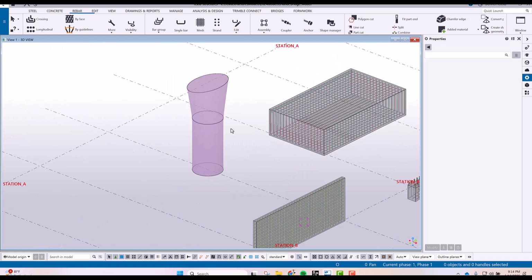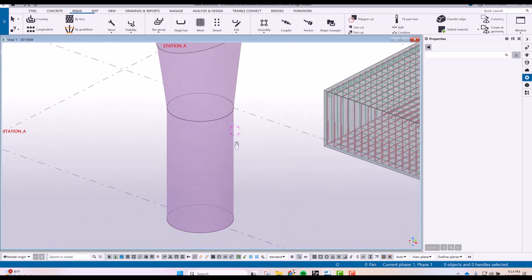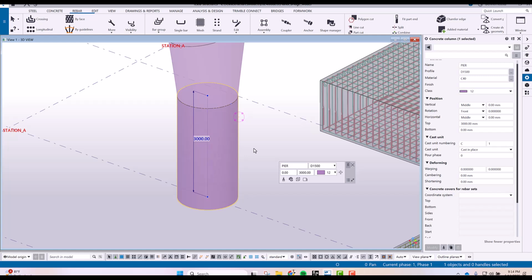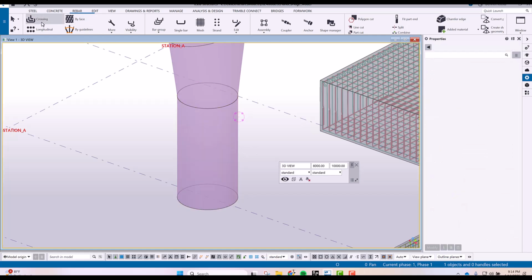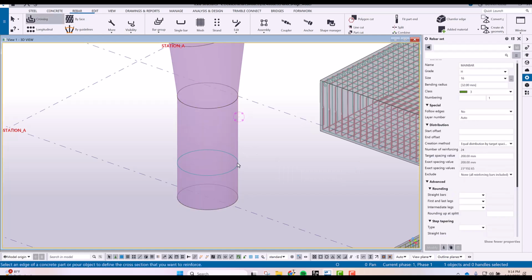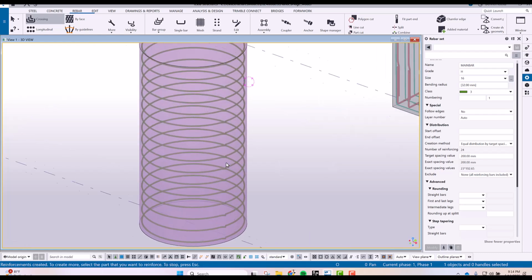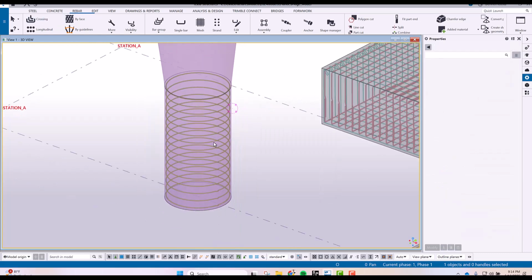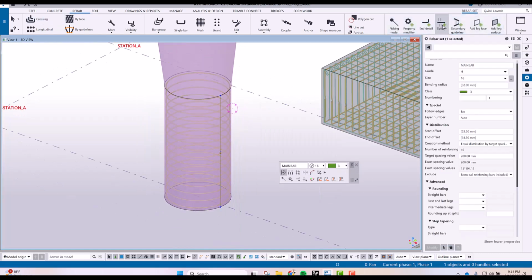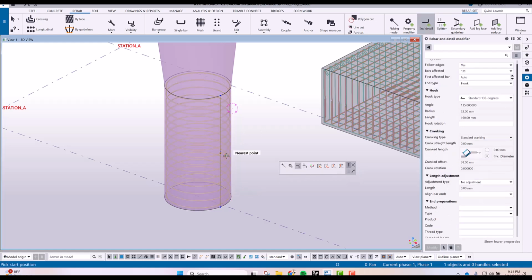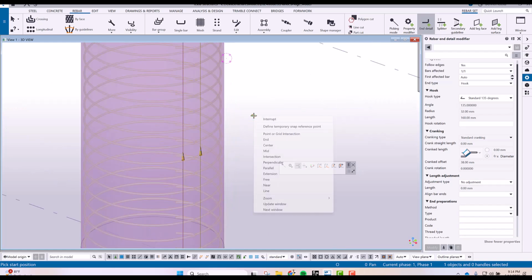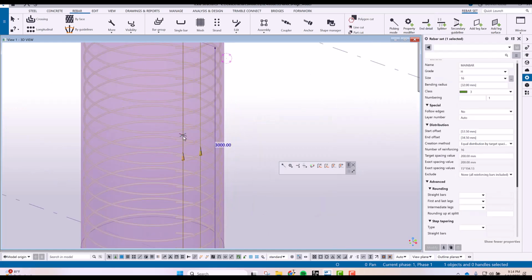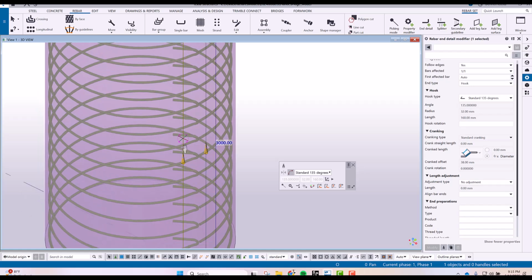Okay, let's move on. How about this one? So here for the rebar set, I can now use my crossing. Look at this. You simply select this one and then middle button of your mouse, then you have now the crossing here. Okay, so let's try to change this end detail. Can we add the detail here? Select this. If you notice here, it bends.